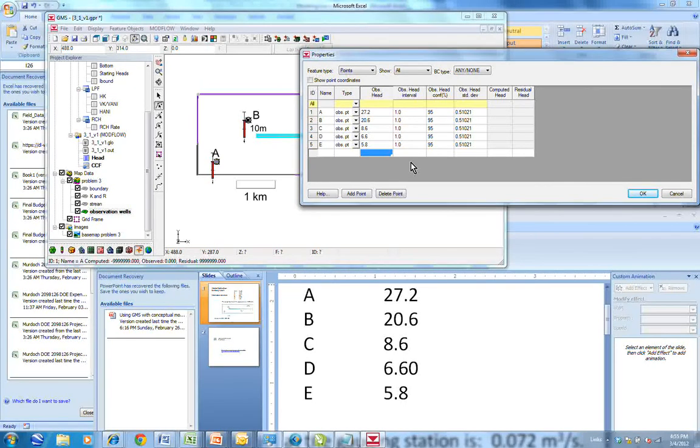And so we can put in the uncertainty in this measurement here. This is the interval, and this is 95% confidence. So if we enter that interval, this would be 1 meter, plus or minus 1 meter is a 95% confidence interval, and then that gives us the standard deviation; it calculates it automatically.